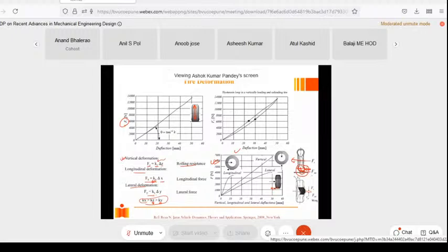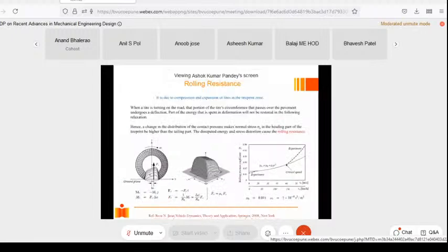Now over the contact region, let us say this is your contact region. When you try to find the total force, it happens that it is not passing through the centroid of your contact area. In that case, there will be some trailing moment arm, and the moment which is generated from this shift is called cornering moment. Okay, so that's what I was talking about. So there are three forces in the tires which are important: longitudinal, lateral, and cornering moment because of the lateral forces.